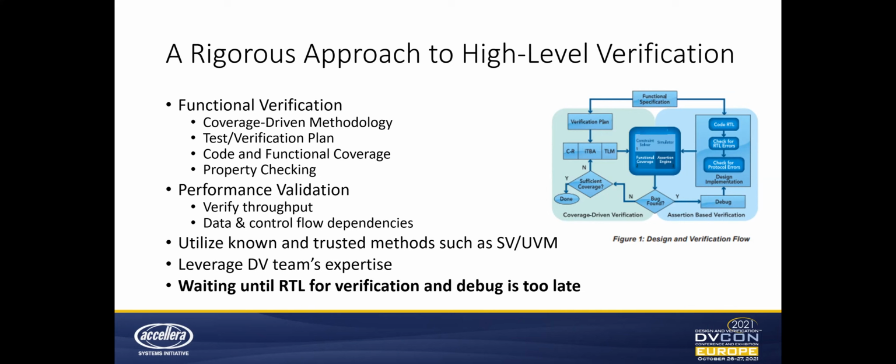This is important because it'll be too late if you simply wait for the RTL before you begin verification in earnest. The size and the scope of the resulting RTL that comes from more abstract C design source can make first level triage of test failures a good deal more difficult. And you'll likely wind up spending a lot more time throwing RTL failures back over the wall to the design team than you would like.